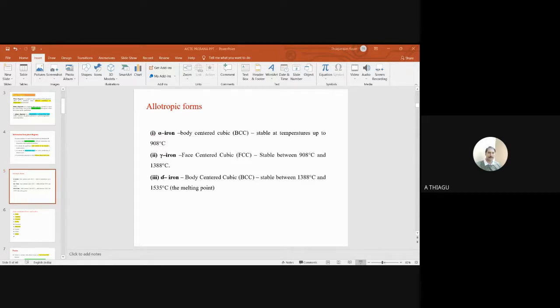The hardness is around 450. Okay, so it is very high hardness. Last one, the 700 Brinell hardness number is attained for the martensite structure. Martensite means austenite is suddenly cooled. So this is the appearance. You can see the lamellar forms. The hardness is very high for the martensite state.